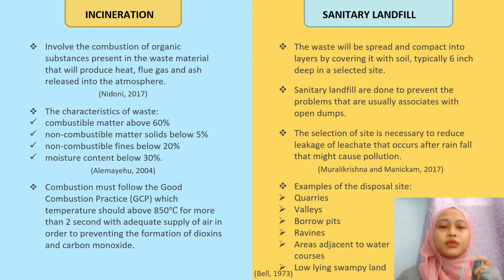Next is sanitary landfill. Sanitary landfill is where the waste will be separated and compacted into layers by covering with soil, typically 6 inches deep, in the selected site. Sanitary landfill is very different from the usual landfill, where there are usually problems associated with open dumps. The selection of site is very important so that we can prevent the problem of leaking of leachate that will occur after rainfall and cause pollution to the surroundings.